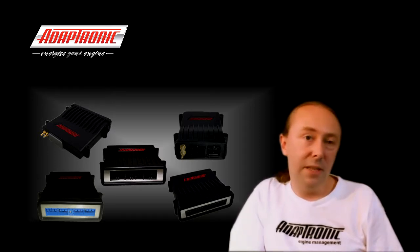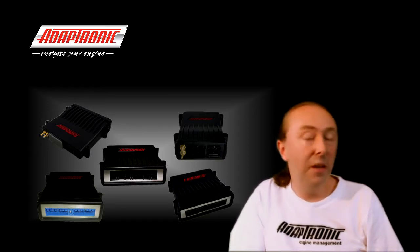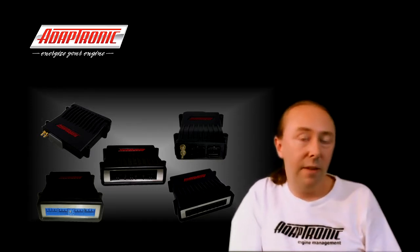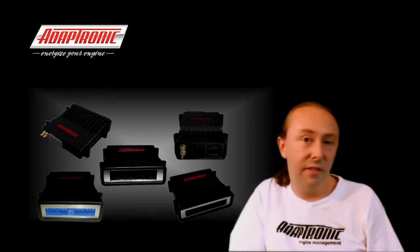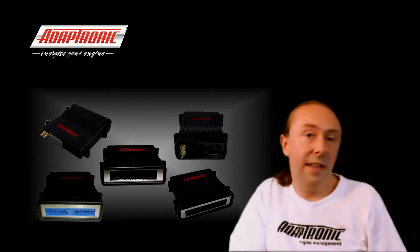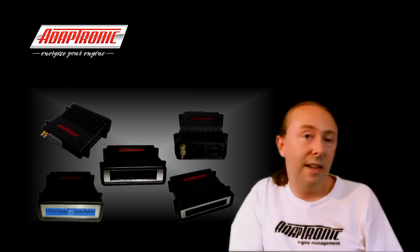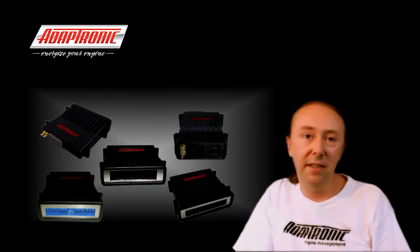Now one last thing I sort of mentioned earlier, doing ignition cut on launch like this does reduce the life of a turbo. For quite a while I was running one of my street cars by just doing retard and enrichment, and it ran for several years like that with no problem. It doesn't make the bang bang bang sound that everyone likes, but it certainly helped build boost off the line. When I started enabling the ignition cut, it was a lot more bang bang bangy, but it reduced the life of the turbo to a few months. Now, having said that, it probably wasn't the most durable turbo on the market, but all the same, just be aware it will reduce your turbocharger life.